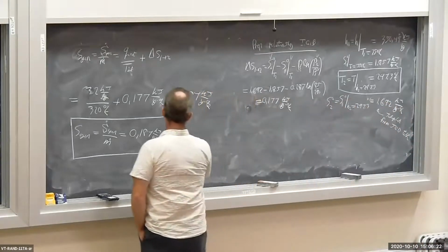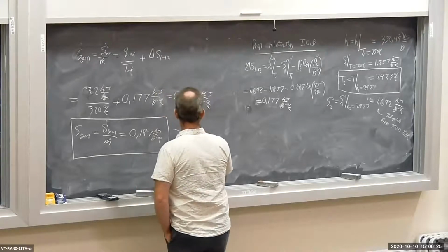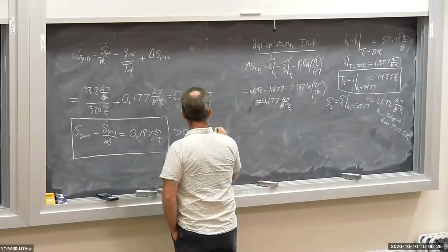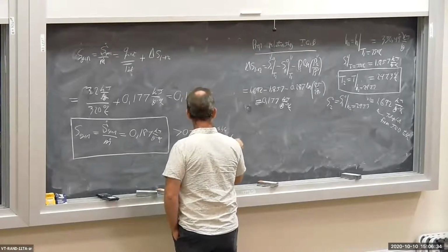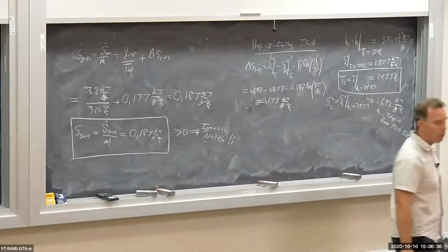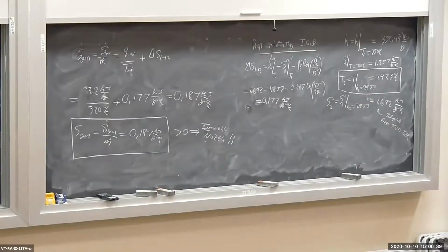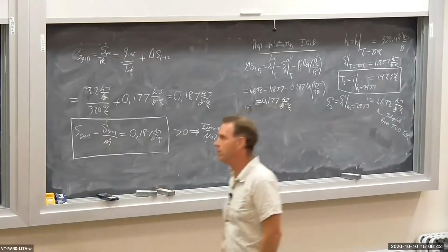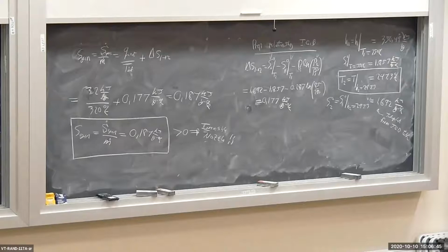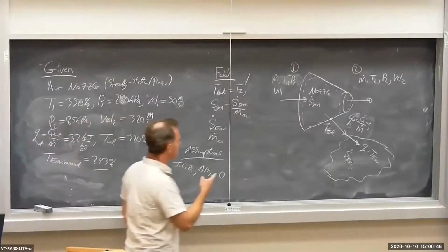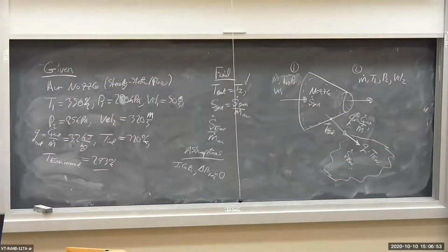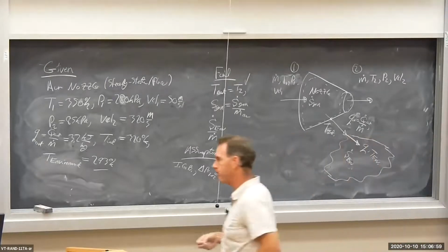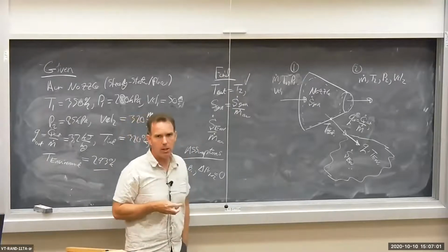So note, greater than 0, irreversible nozzle. Irreversible. So there's some friction going on in there. There's some unconstrained expansion. We got a pressure drop across the nozzle, high pressure, low pressure. Maybe the pressure isn't dropping reversibly. Maybe there's some weird fluid dynamics going on inside, some flow separation. All sorts of stuff can be going on. There's mainly friction in there, probably a lot of friction.